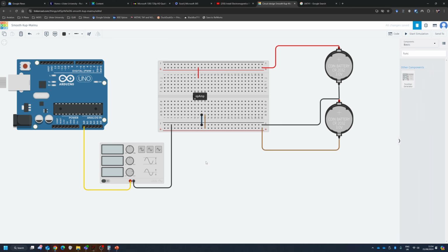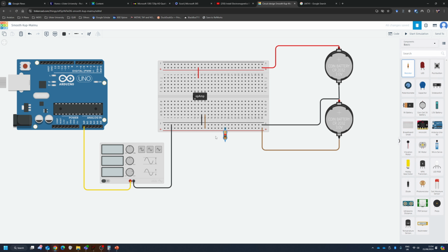So let's do this. I'm going to press here to add a resistor. I'm going to rotate this resistor. And I'm going to place it here, should be good. And oh no, this one is my feedback resistor, so let's add it in between our input and output. So in minus goes one wire here.